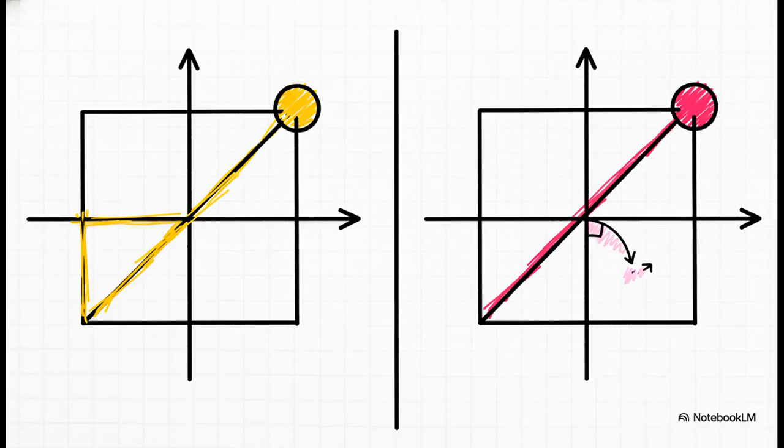When we get down to the math, we do this by taking our system's transfer function and just swapping out the complex variable s for j omega. We can then represent this response in two ways, either as a complex number with real and imaginary parts, your r and x, or, and this is way more intuitive for what we're doing, as a magnitude and a phase angle. It's the exact same information, just a completely different coordinate system.